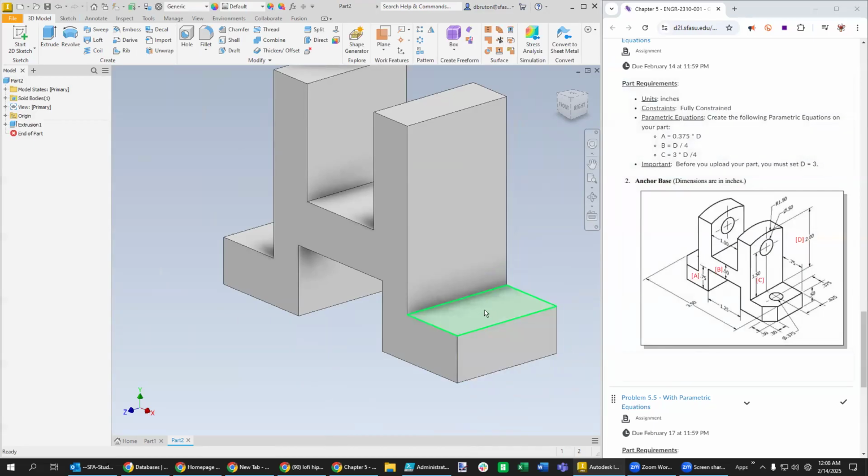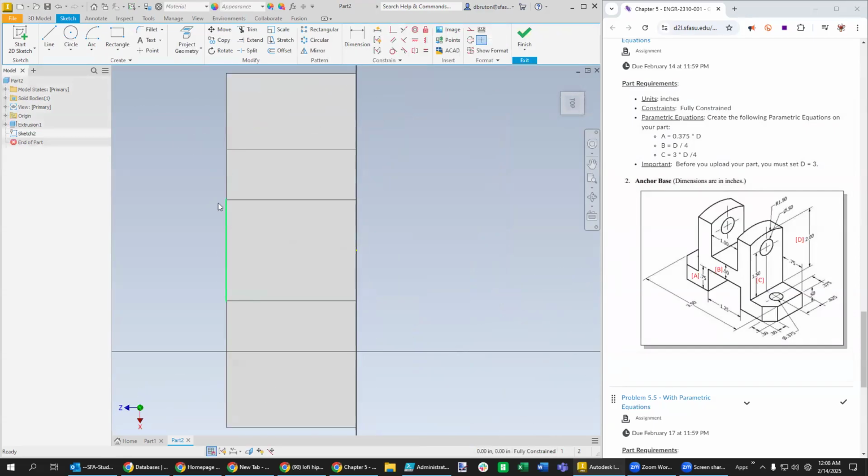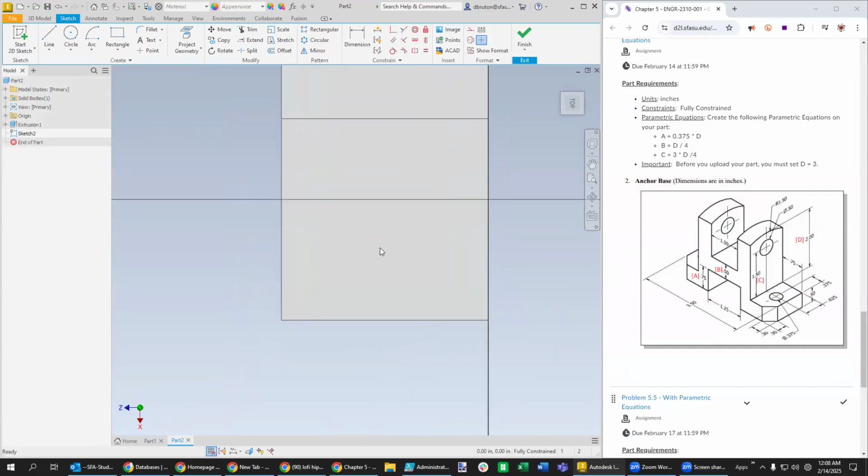And we can start to put some holes down on this surface here. So let's try to do it on this side and then mirror it over on the other direction. So let's right click here and go ahead and create a sketch right there. And it's going to be the circle that we see as well as the triangle. So we could say, let's make it a midpoint there, but let's just not assume that's the case. It looks like I got my locking feature in position here. The snapping going on like that.